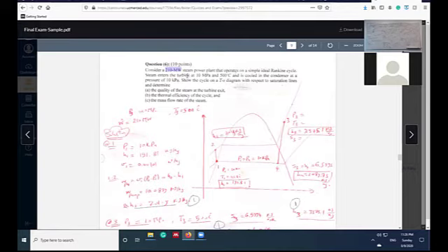It was operating the steam air into the turbine at 10 megapascal and 500 Celsius. So I give you stage 3, completely stage 3, P3 and T3. Can you see this? P3 given and T3, which is a superheated vapor. This temperature is so high and this pressure is so low. It means you have superheated, table A6.